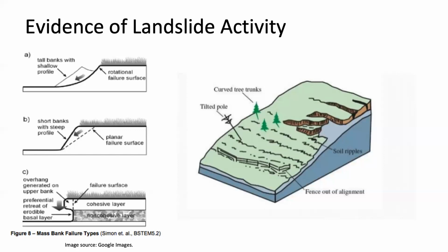So these are all failure modes that can happen relatively acutely, relatively quickly. And then there's a creeping slope failure, which is a much slower long-term superficial slope movement characterized oftentimes by curved tree trunks, ripples on the slope surface, leaning posts, and accumulation of mobilized materials on the slope.